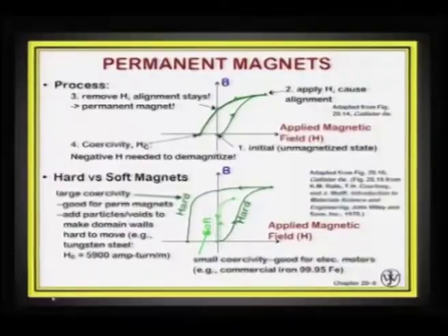at the hysteresis loop. As you know, the hysteresis loop tells us about an unmagnetized state or a virgin state of a magnetic material. On application of a magnetic field, it gets saturated, and then when you remove or reverse the field, it loses its saturation, and this is the remanence that you get out of it, and then you can completely remove the magnetization, or demagnetize, when you reverse it. Therefore, your response in the second quadrant becomes very important for your permanent magnetic material.